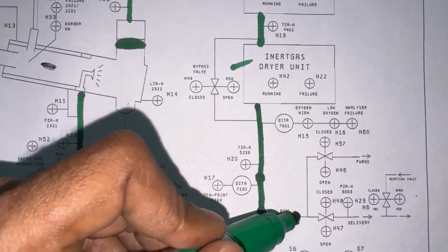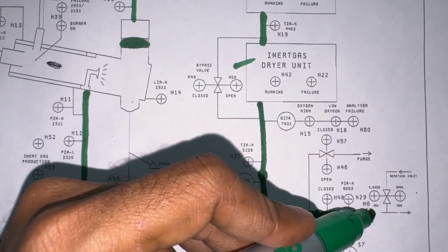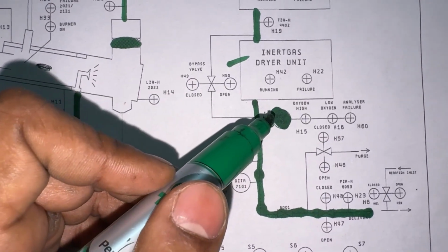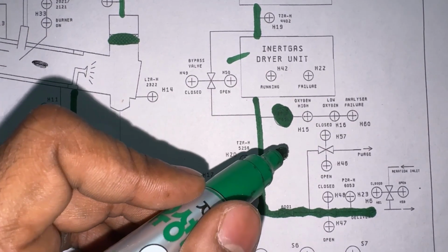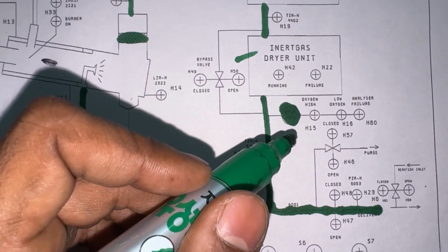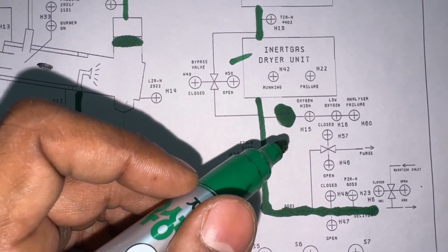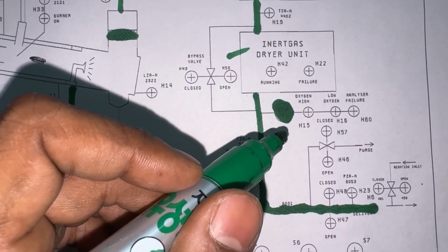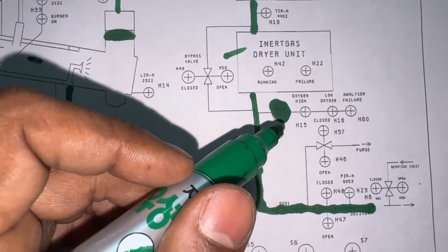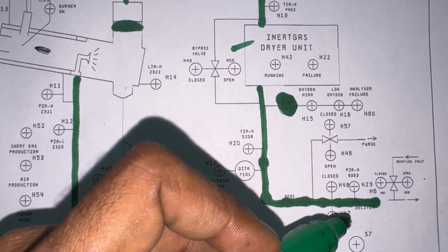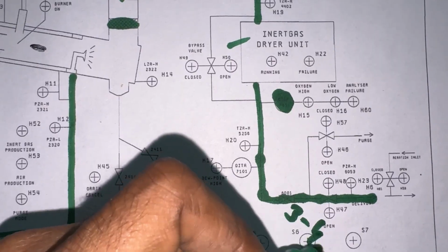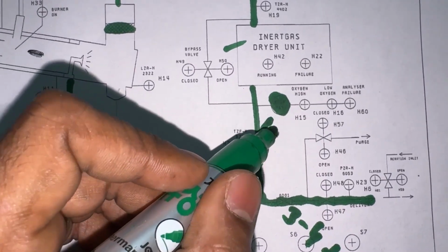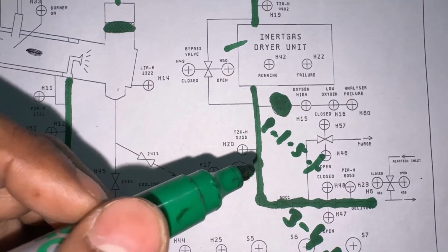will go to the cargo hold space tank only if this oxygen analyzer is showing oxygen 1% or 1.5%, because if the oxygen analyzer is showing O2 content 1% or 1.5%, then the oxygen going in the tank is around 3 to 4%. That is why it should show around 1 to 1.5%.